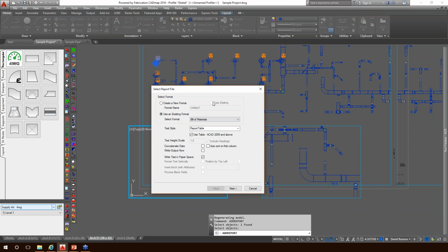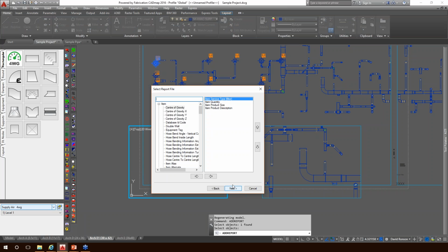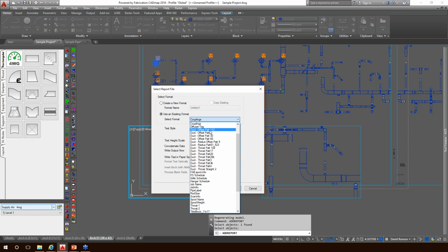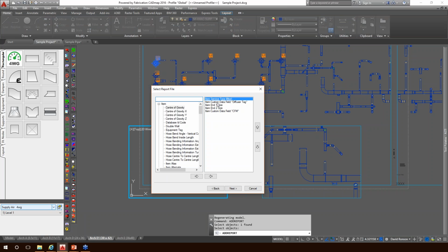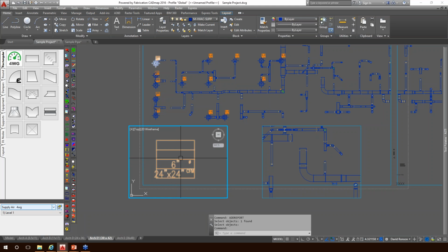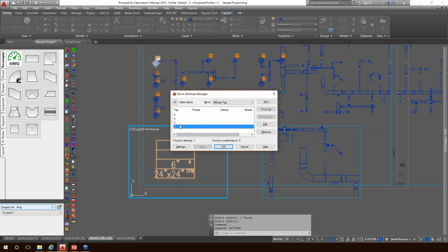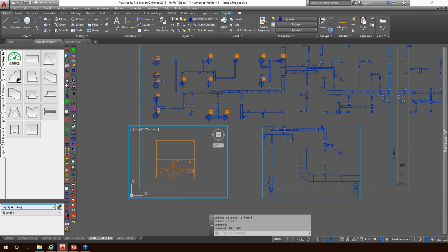In the ad report, it's going to apply that in the same order that you're calling for it, okay? So if that happens to you, you can reorganize your attributes inside the block in the correct form, and they'll come in correctly, okay?